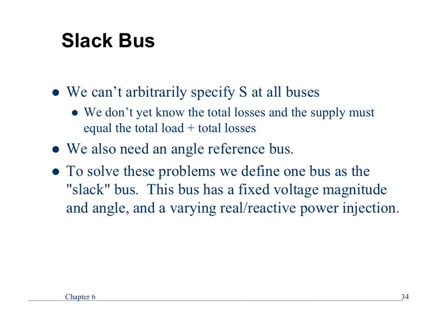So a slack bus is another bus sometimes called an infinite bus or a reference bus. It could also be called a voltage bus. And the reason being is, at a slack bus, you know the magnitude and the angle of the voltage, okay? You know V and theta. And the reason why is because you have to have a reference point at some location. You have to say, I know a voltage at this location and an angle. You need a starting point, essentially.